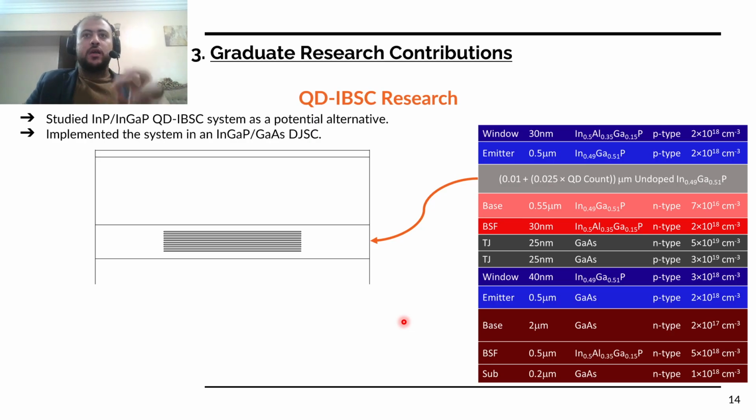So I just want to point out again that quantum dot layers, which we will mention again in the next slides, mean the horizontal layers that usually should contain uniform quantum dot distribution. This is the first thing. The second thing, we simulated a whole stripe of quantum dots, and we defined periodic boundary conditions along the x-axis. So if this strip is repeated, it will give the same results.